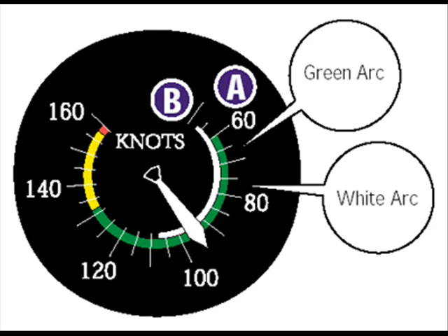The sudden and often dramatic increase in stall speed could place you near a stall before you can accelerate to a safer speed. Apply full power first, then retract the flaps in increments. In airplanes with 30 to 40 degrees of flap extension, retract the flaps to their least drag, maximum lift position. Usually this position is found at 1/2 flap travel, depending on the airplane. In airplanes with 3 notches of manually applied flaps, retract 1 notch first, followed by the other 2, once the airplane begins to accelerate.